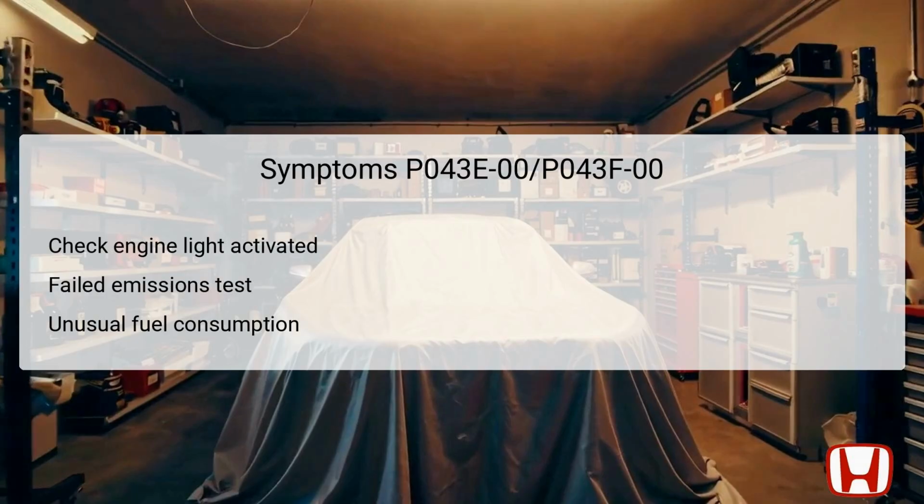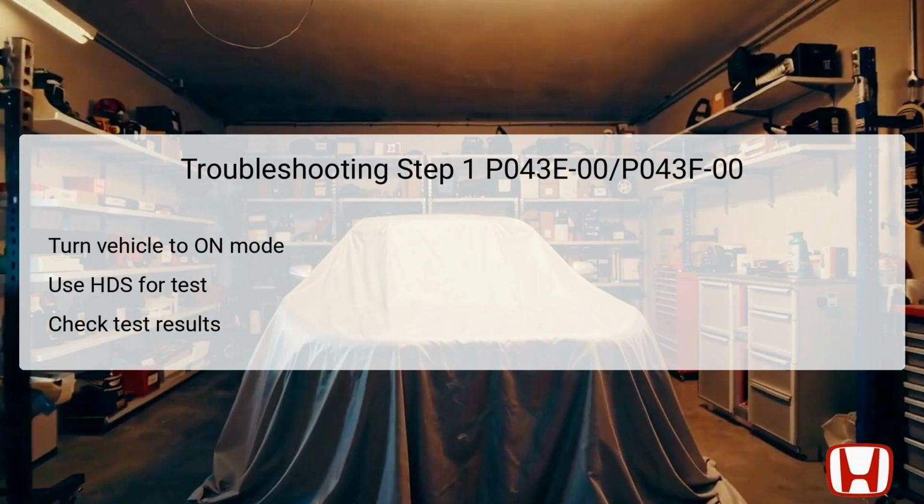overall optimal operating conditions. The first step in troubleshooting DTC P043E-00 and P043F-00 involves bringing the vehicle into the on mode without starting the engine.